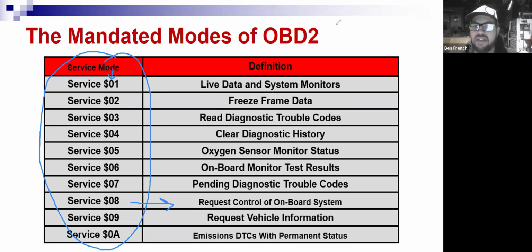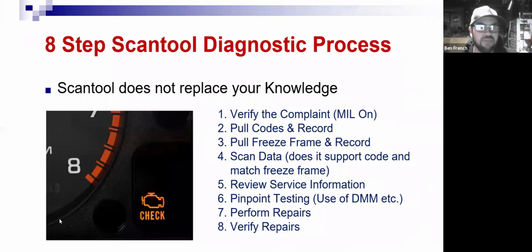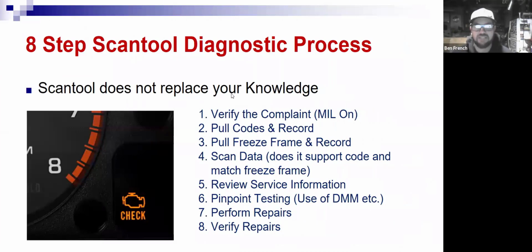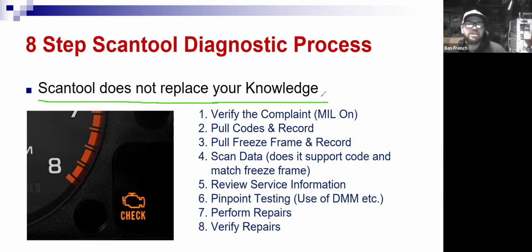Then in our class we started on the diagnostic process. I can't stress enough that the scan tool doesn't replace your knowledge. It's a combination of using the scanner to its maximum ability and using your service information. There's a reason we don't clear the codes until we've performed our repairs and then verified those repairs, because we want to make sure we truly fix the problem.